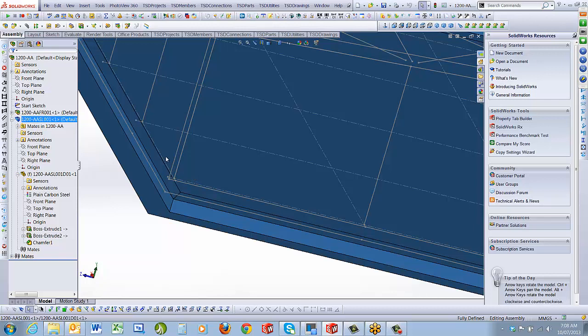The tilt panels themselves are a bit different to the panel clad panels because there's two particular types. There's panel clad panels which you can actually cast and make inside a building, avoiding things like weather affecting the progress of your project, or you can do tilt panels which are actually cast on site and they're face lifted and then edge lifted into position and sit on dowels. The panel clad panels actually clip to steel sections, columns and such, to hold them in place. And they use friction plates to clamp them to the columns. So they're a bit different in the design between the two different types.